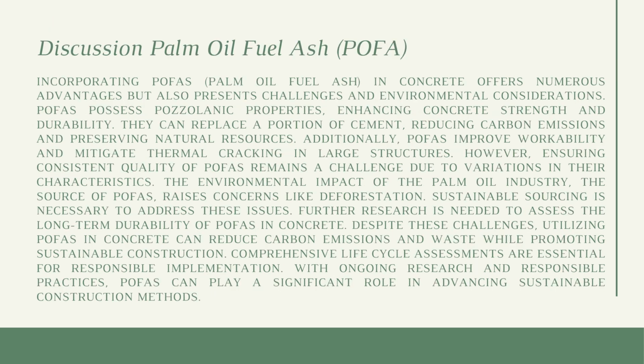For the discussion of palm oil fuel ash, POFA enhances concrete strength and durability. It can replace a portion of cement, reducing carbon emission and preserving natural resources. Additionally, POFA improves workability and mitigates thermal cracking in large structures. However, ensuring consistent quality of POFA remains a challenge due to a variation in its characteristics.